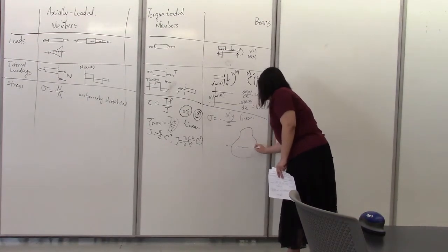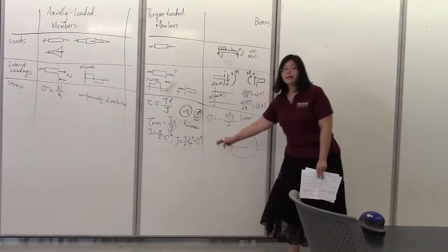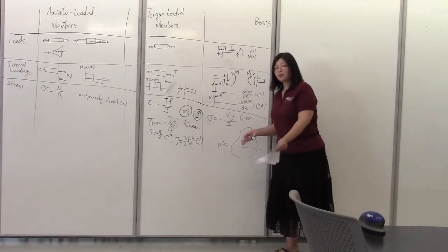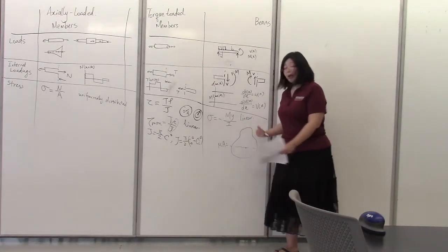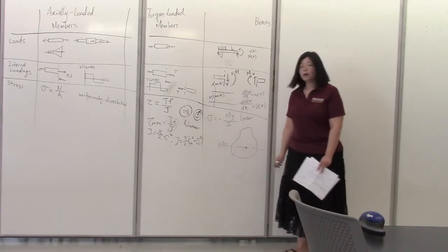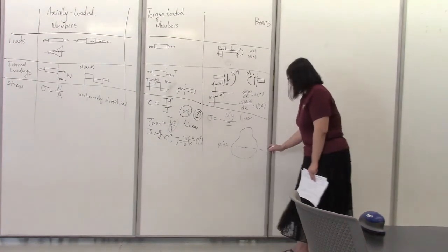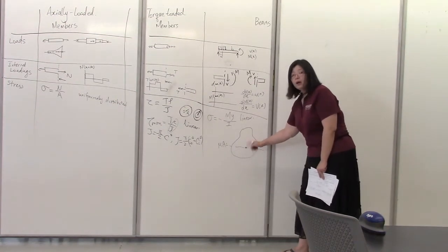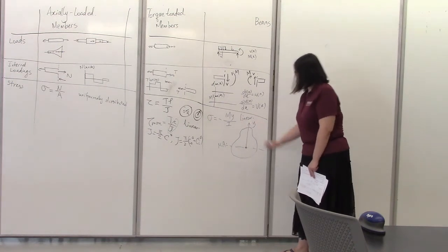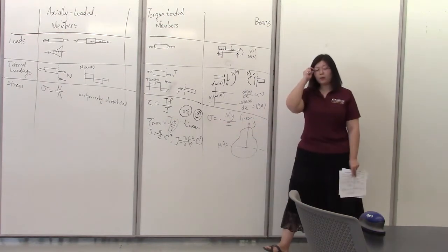For any beam cross-section, we have a neutral axis. The line segment along the neutral axis is neither compressed nor stretched. The neutral axis passes through the centroid of any given beam cross-section. So y is defined to be 0 on the neutral axis, and it is going up. So this normal stress can be positive or negative.